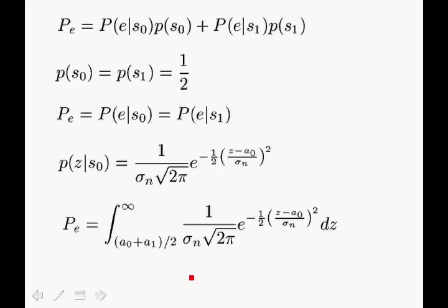So here we have the expression for the probability of error for the baseband digital communication link. The performance of a digital communication link will be determined by the probability of error versus the signal to noise ratio, or as we will point out, the Eb over N0 ratio, where Eb is the energy per bit and N0 is the one-sided noise spectral density. However, we need to come up with a more compact expression for the probability of error, and to do that we introduce the Q function.